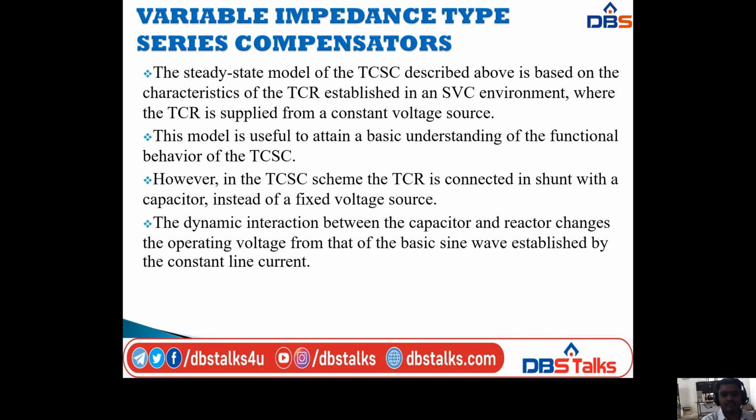However, in the TCSC scheme, the TCR is connected in shunt with the capacitor instead of a fixed voltage source. So in the fixed voltage source place we are connecting the TCR in shunt with the capacitor. The dynamic interaction between the capacitor and reactor changes the operating voltage from that of the basic sine wave established by the constant line current.